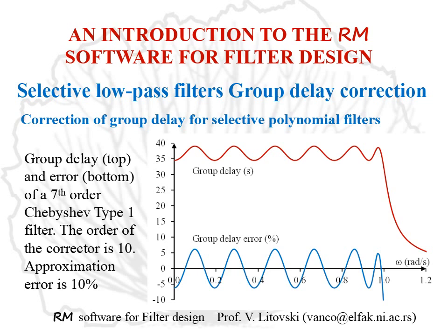The counterpart of the LSM is the Chebyshev filter, and here seventh order Chebyshev filter is considered, which approximately has the same selectivity as the ninth order LSM.